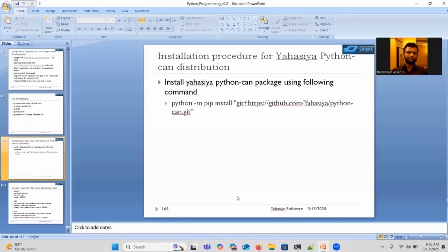As part of continuous improvement, we integrated RabbitMQ server with Python CAN library. What is Python CAN library? Python CAN library from Hardbyte is the widely used Python library in the automotive industry for exchanging packets between real hardware and Python, right?